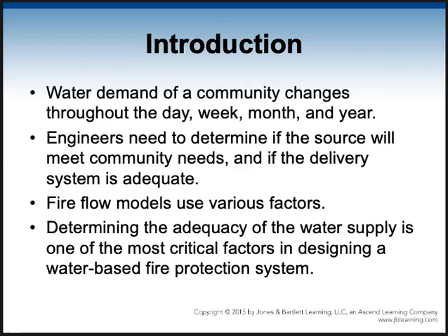Fire load is the stuff in a building that will burn. So these engineers will figure out, before even putting together a fire protection system, how much heat is going to be produced in this building as a result of a fire. And it's going to make a difference how the building was built. Is it built out of concrete, wood?